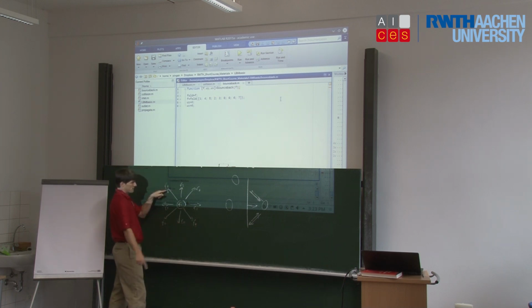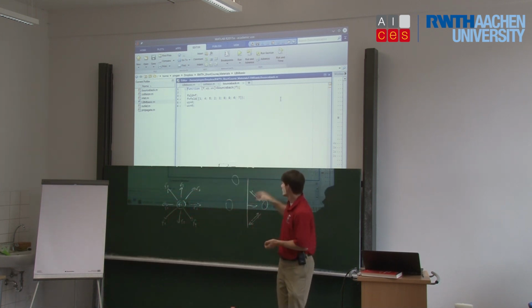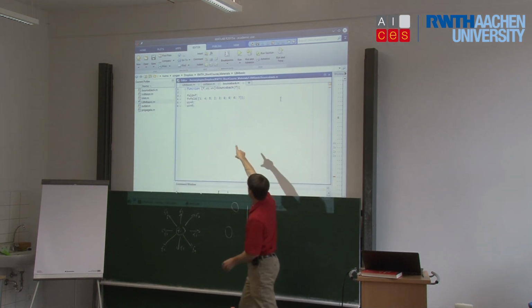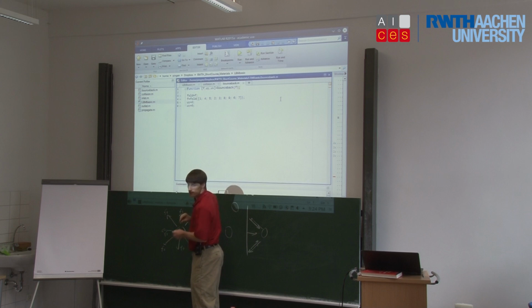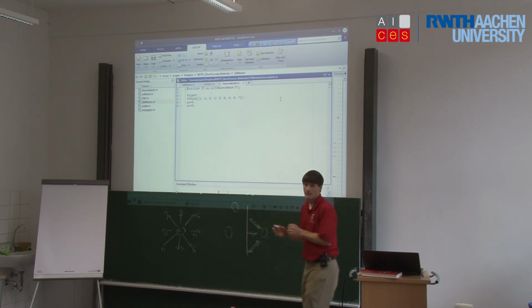And these are just: F9 becomes F7, F6 becomes F8, F8 becomes F6, F2 becomes F4, so they're just reflected back to where they came from. And so that's really what we do right there, we basically just say F is equal to the old F, but with the different entry points. So we have these 9 different velocities, and we just reflect them. Okay?